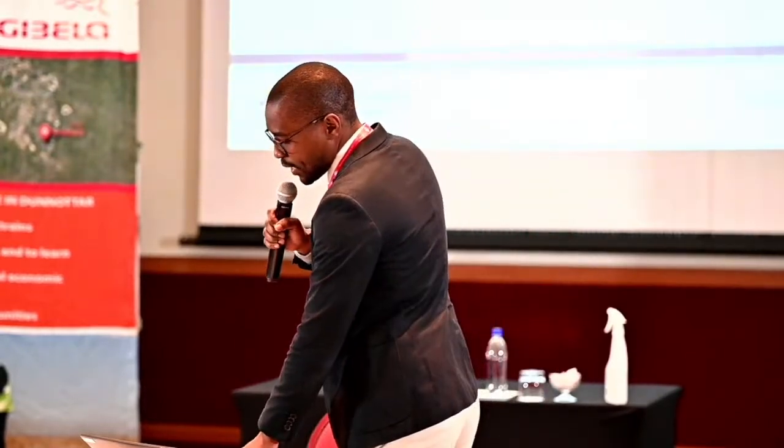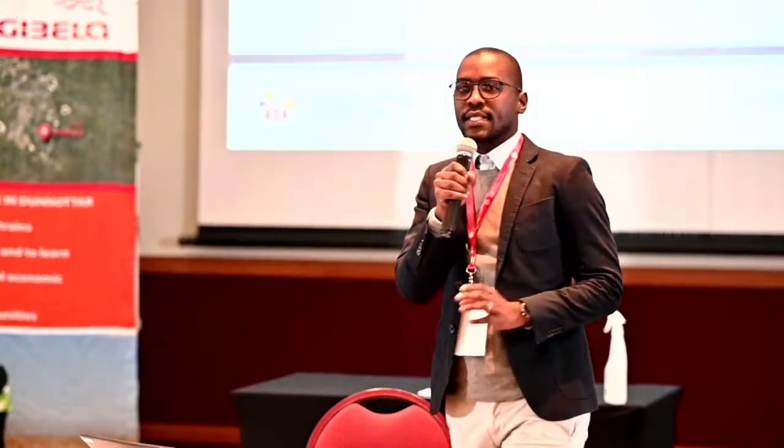With that, I categorized it into the substations, the feeders, the duration of the fault, and how early it was cleared, and with that I was able to calculate the SAIDI and SAIFI. The last stage is analyzing this actual data to show what is leading to these faults and how we can mitigate them.